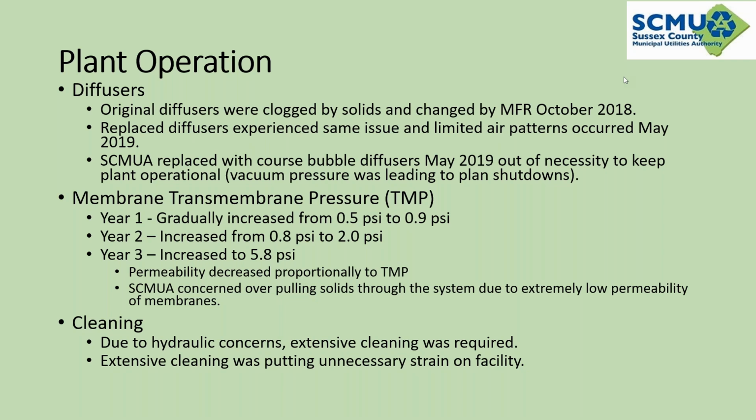And then you may want to have an acid clean as opposed to a hypo clean. And then you have to go even further. If that's still not doing it, you've got the extensive recovery clean, where you have a higher concentration of the hypo, and then you have a longer period of soak.